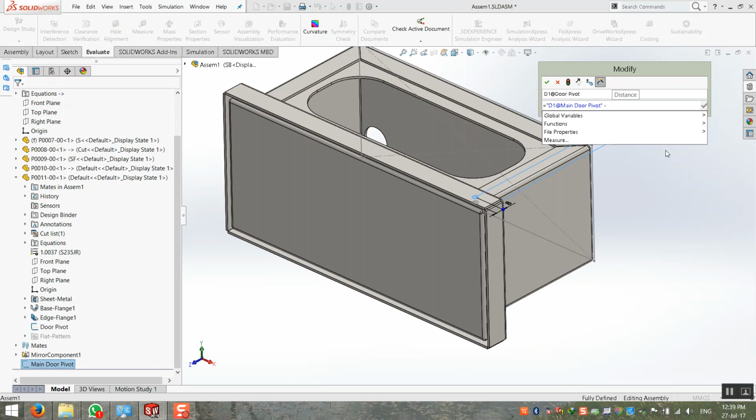Because this 5 already has 2 factors, 3 and 2. Each factor can be changed in future. You don't know. You may change your thickness of sheet metal. Okay, you may change the gap. So you write minus 3, minus 2. Separate it, because when you change the gap, you can change only the 3, without making the calculations again. Okay. All right.